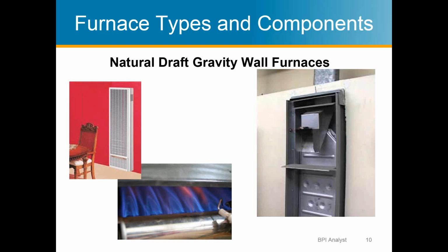Yeah, that's a great point, Mike. And what we see in these wall furnaces is that it could be functioning just fine, but after you air seal a house, it may not operate well anymore, because you need makeup air that these old systems assume you have.